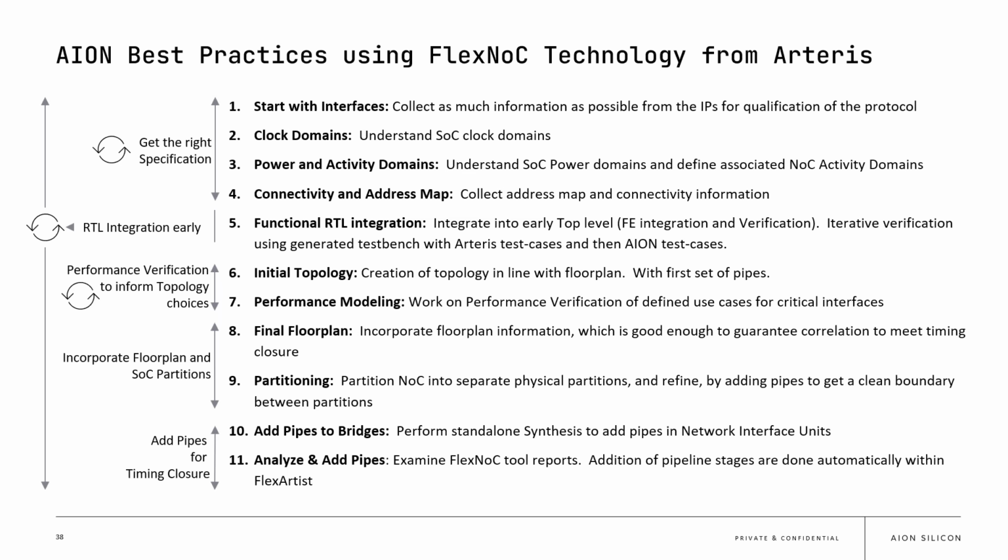And then step 5, start your RTL integration early. So RTL integration includes RTL verification. You want to start this early because that ensures your integration team have a NoC to start integrating and make sure that all their flows are pipe cleaned.